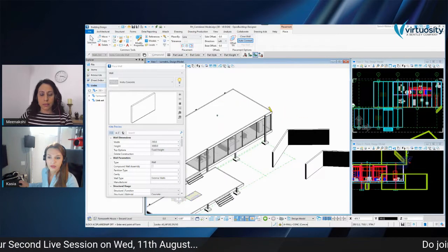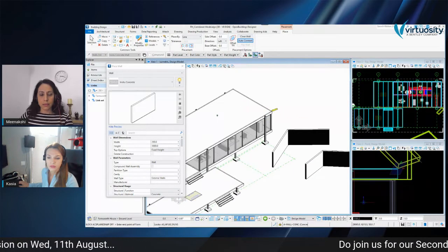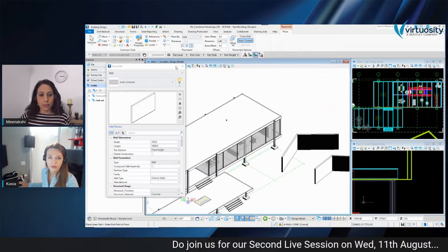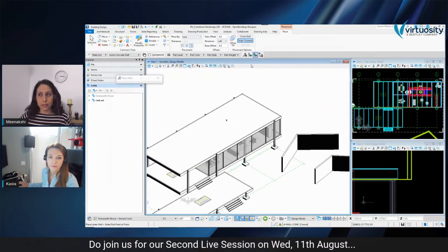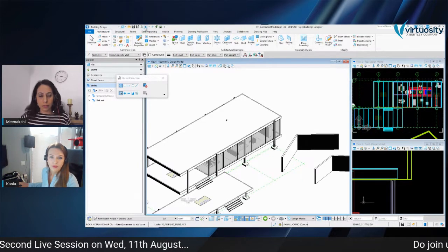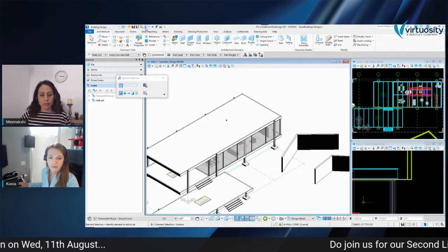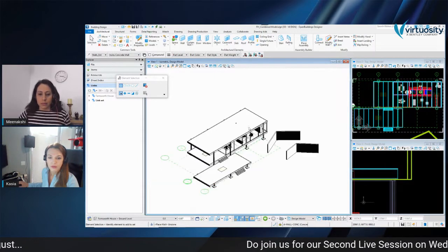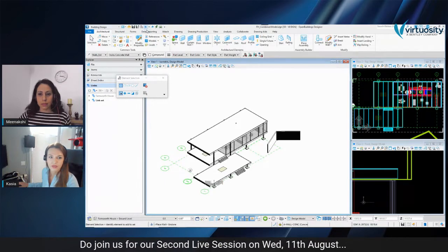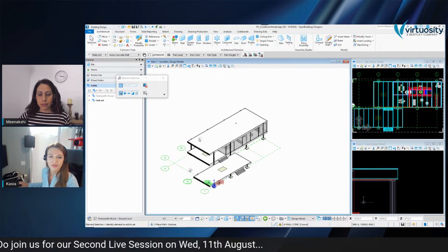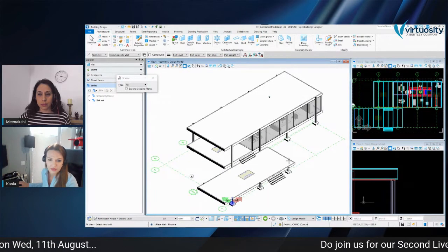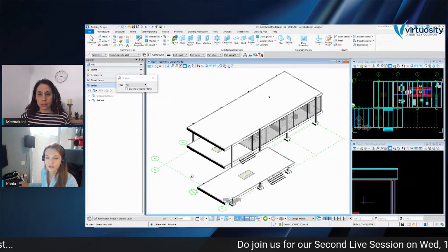As you can see, now it's not at the roof level, I'm snapping to the element, unlocking this feature to lock to the active plane. So I can remove the walls now. That's why it's useful, because sometimes it can happen that we lose one of the elements somewhere in the file. It doesn't happen if we have this floor selector option.